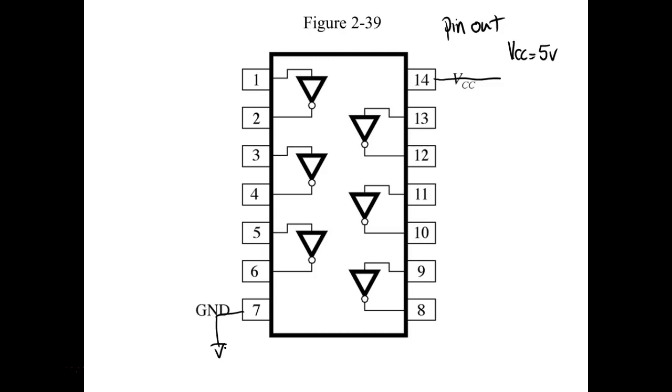As soon as I do that, I've powered up all 6 circuits inside the IC. If I wanted to hook up to this guy, I would bring this signal in on pin 1, and I would hook up whatever I'm running with this inverter over to pin 2. It has nothing to do with the one next to it. It's just a different circuit inside the same package.